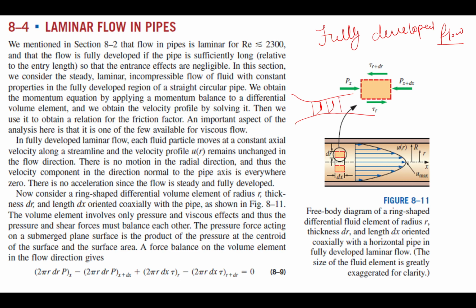Here is little bit less. And after some distance your velocity diagram is parabolic kind of thing, similar to this, and after that there is no change in the velocity diagram. Everywhere you will find the same velocity diagram. So the distance traveled from the initial position up to the fully developed region is known as the entrance length. Whatever analysis we do is in this region, not in this region.